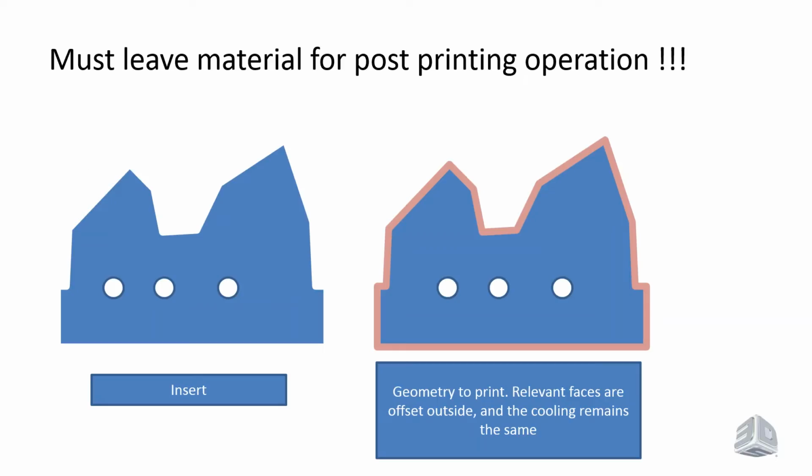So thinking about what we said about your CAD system, you have to be able to offset the faces inside that uniform distance so that you can build your conformal waterline in those hard to reach areas. But also all over the part, we're going to have to offset those core faces to the outside so that we can have the minimum material that we need in order to finish mill it once we're done. So we're sending that model right to the printer with the offset. Now, if you just took it to a CNC mill and we're going to rough it, you could take your finished core geometry, say, let's leave 20 thousandths, 15 thousandths, and the cutter won't go in there. Maybe we've been a little spoiled by that. That's a nice feature to have. When it comes to this, though, we're sending a 3D model to the printer. That geometry has to be on that 3D model. It's not something that we can have the machine fake it for us.